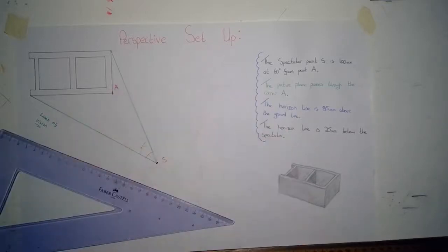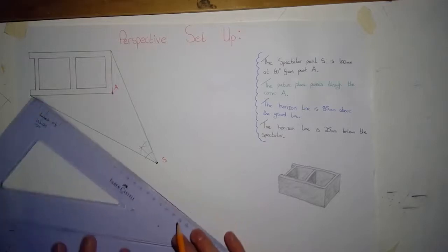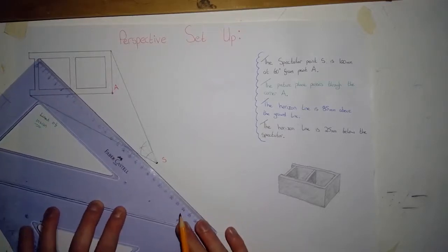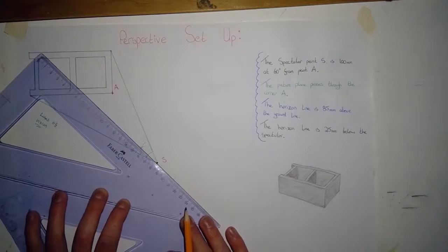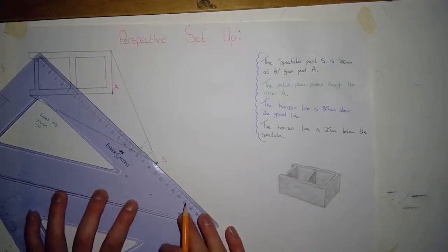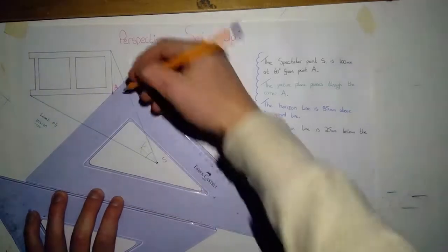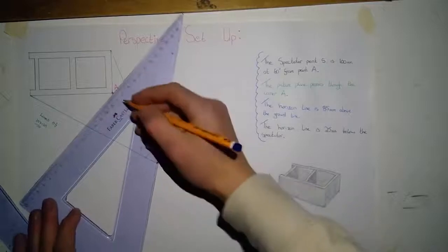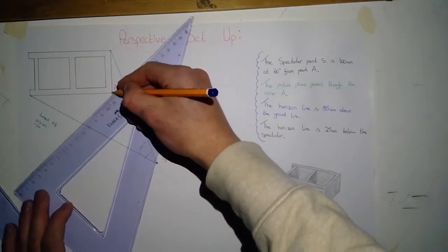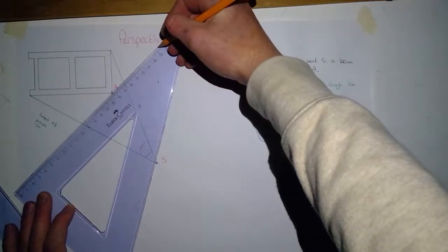So the next question is, how are we going to get what angle it runs through corner A? We get this angle simply by going perpendicular to this bisecting line that we have drawn. So we set up sliding set squares and we draw this picture plane line perpendicular to the bisecting line of the lines of vision.